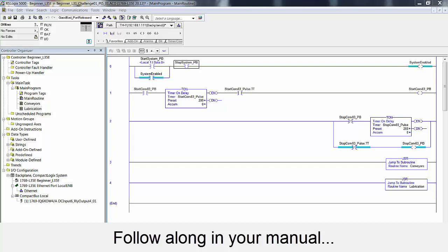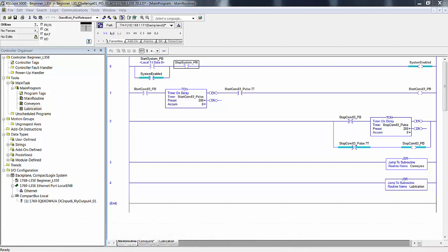Each conveyor has an entrance photo eye, the location of which assumes that when a carton comes to rest against the leading edge of that conveyor belt, the carton is blocking, sensed by, the photo eye at the entrance of that conveyor. Meaning that if a carton comes up to conveyor 1, even if conveyor 1 is not running, the leading edge of that carton is far enough into the beam of 1 PE that it is blocked, so 1 PE or local 1 I data 1 knows that there's an object there.